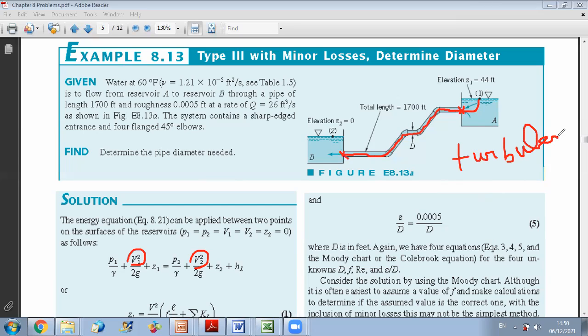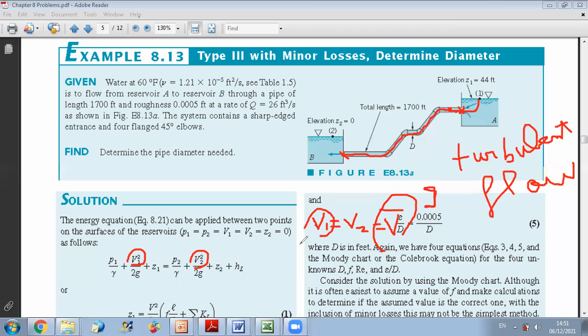When you assume turbulent flow, we saw that usually the profile is very close to a flat profile. This is why if you apply Bernoulli in turbulent flow, you can assume that V1 and V2 on the streamline, which is at the center line, are nearly equal to V average. Why? Because in turbulent flow the profile is nearly flat, unless they give me a profile. If they give me a profile and I can find the average and the center line velocities, then there's no need for this assumption. But if they don't tell me anything and I assume turbulent flow, I can consider that V on the streamline at the center of the duct is equal to V average because the profile is close to flat.